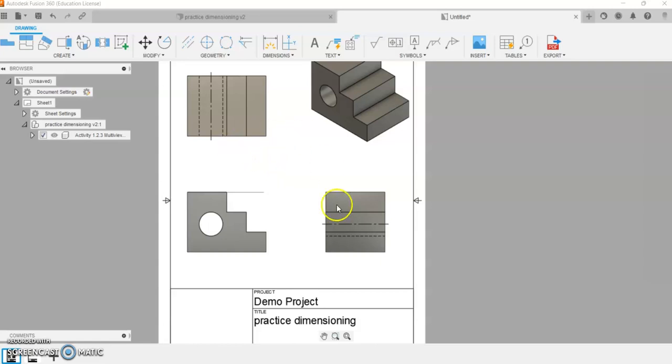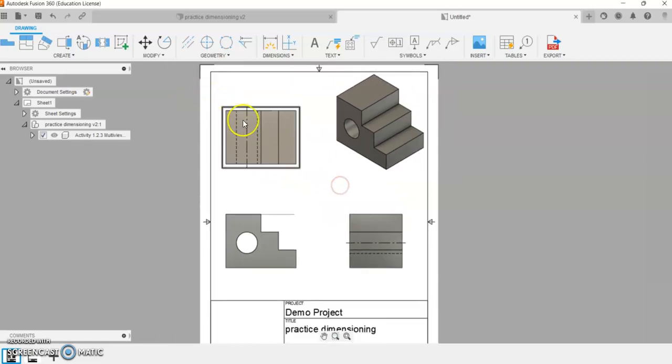That's okay. So where we had left off was that we were putting center lines through our hidden lines of our hole here. So we're going to pick up right from there. We have our center mark now. So now that I can see the front face of the actual geometry of this circle, which again is the same one here, I'm going to go ahead and select from my ribbon the center mark. I'm going to select the outer diameter ring, and that's going to tell me exactly where that is. Okay, so now I'm ready to dimension.